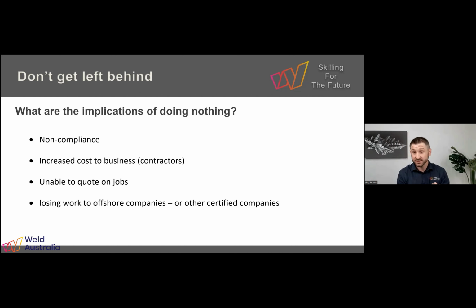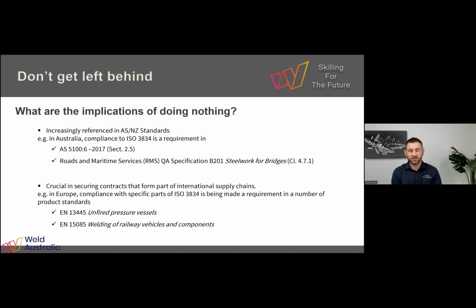Now, I talked earlier, this is referring to 3834, right? It's increasingly referenced in Australian and New Zealand standards. AS 5100 and the RMS in New South Wales, Steelwork for Bridges, they specify that you need to be 3834 certified to even tender on their jobs. A lot of the European standards are making it a requirement, so EN 13445, unfired pressure vessels, and welding of railway vehicles and components. They all specify 3834 company certification to even tender on those jobs.